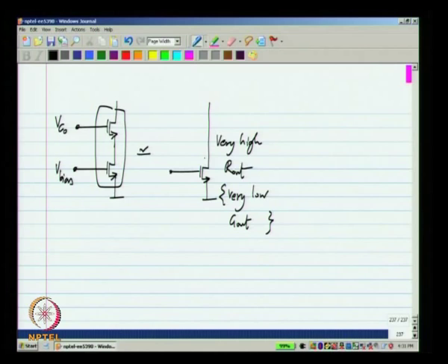while synthesizing circuits, because we are putting more transistors. It looks like a very different circuit from before, but you can think of this combination as a transistor by itself. We know that the transistor is a voltage controlled current source. If I apply Vi here, I get Gm times Vi over there.